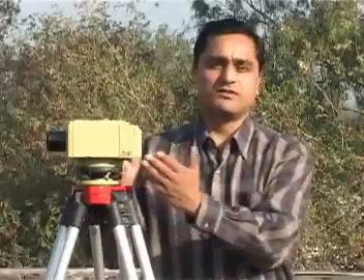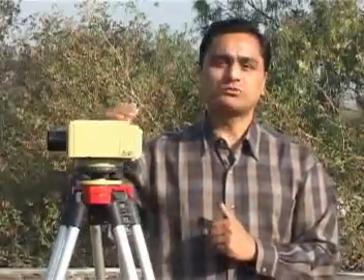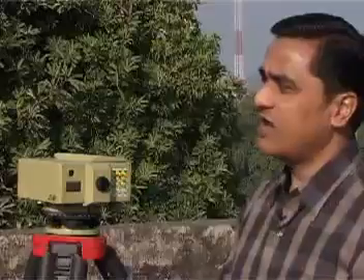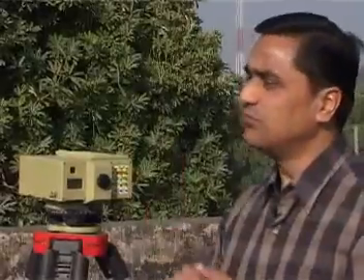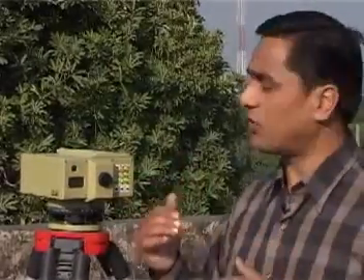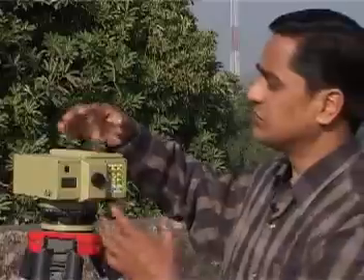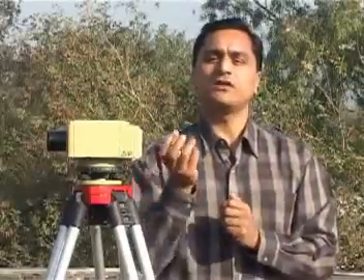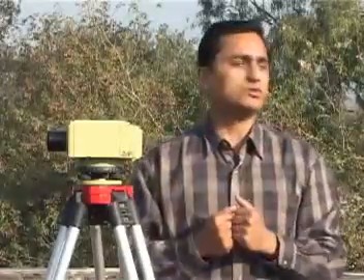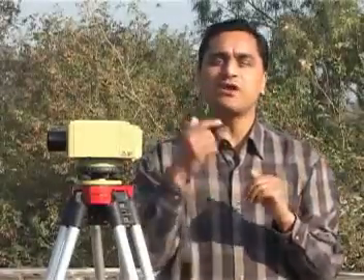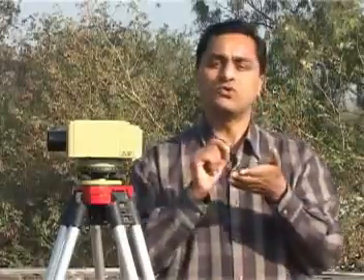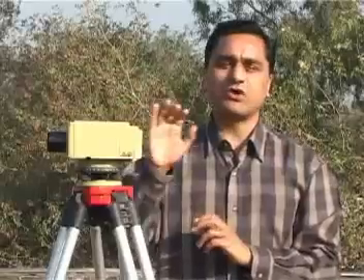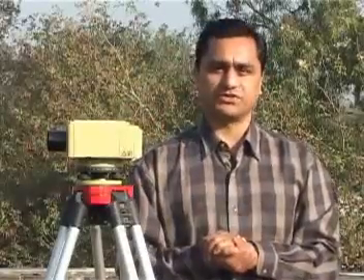In this instrument, the advantage is that all these observations you are taking, you're not recording them manually. The instrument is recording them. You need not write them in a field book. Rather, these observations are recorded inside the memory. So you take the instrument back to the laboratory, plug it into the computer, and download all the observations. The errors which may otherwise occur due to manual recording are also eliminated in this case. So this is used for very precise leveling operations.